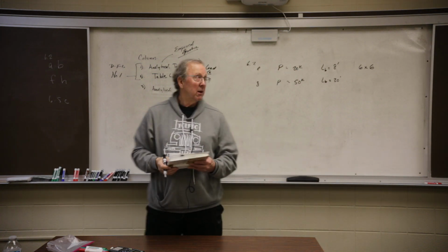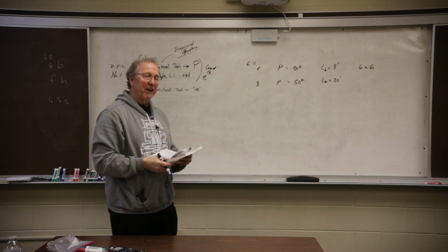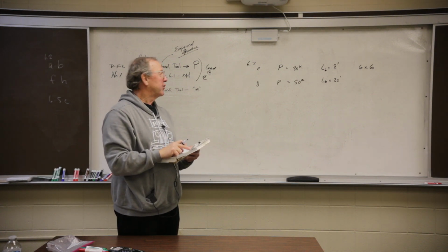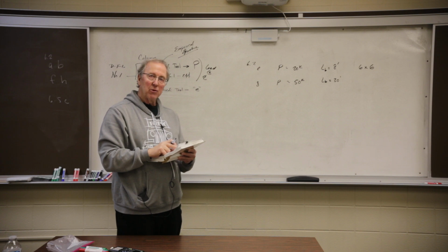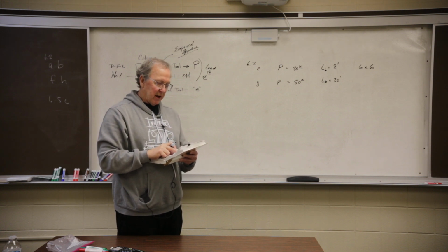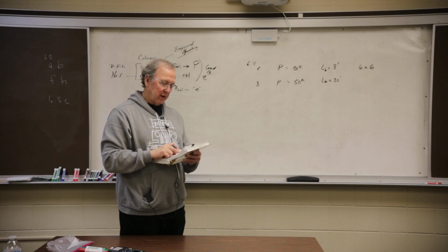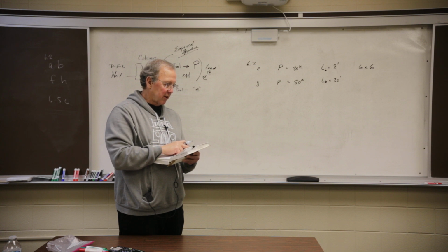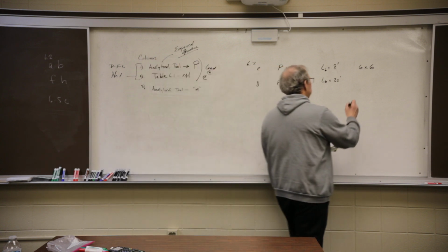Next one, go to the table, put your finger on 20 feet. Head down the column and stop when you get the number that is equal to or a little bit bigger than 50. 7, 9, 13, 23, 29, 35, 52, 52.9. Go across and it's a 10 by 10.